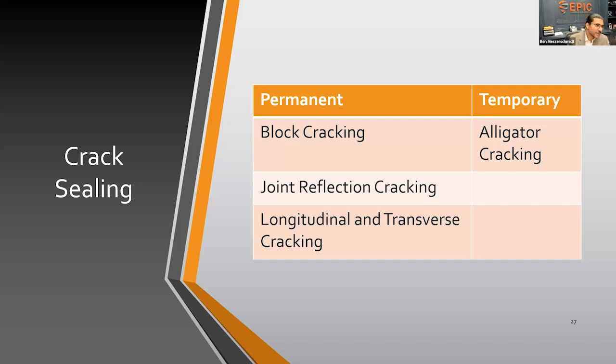So let's say within a clubhouse area, you really just have a lot of transverse and longitudinal cracking. But on your main run, you have a fair amount of rutting along your main drag. And those are going to be two entirely different repairs, but getting some quantities for that is going to be crucial for your financial forecast. It's going to be an easy way to go ahead and normalize any sort of construction bids you may be getting back.